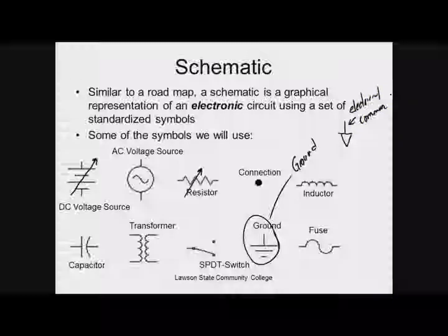Okay, y'all understand that? This is the symbol right here for electrical common. So my cell phone does not use a ground. It's got a what? A common. But you'll find out just about everybody calls a common a what? A ground. So you go out there on your car, this is the return. That's what it is. Of course, you got to understand AC. The return is doing what? Yeah, swapping. So in AC, we refer to it as a neutral.